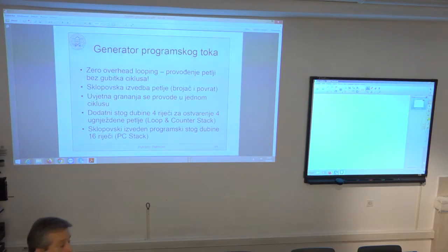In this case, you have to perform some kind of instruction-based memory stack implementation to store the 17th value in the memory, and then it is less efficient. But nevertheless, these internal levels of the nested loop are very fast, because they take the return value directly from this hardware stack without any fetching from the memory.